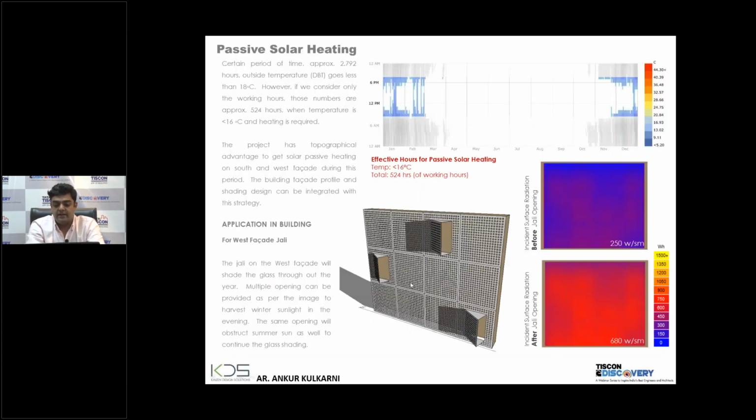Yes, this is again interesting because the architect was very, very keen to have a double skin facade. The idea is, of course, to create a nice play of light and shadow. Similarly, it should reduce our heat load by having this jali, because the jali effect is very, very important to reduce your heat gain. But at the same time, because of passive heating, we kept these few, if you see, 3 4 different windows, a little open, welcoming the sun exactly perpendicular to the sun position,